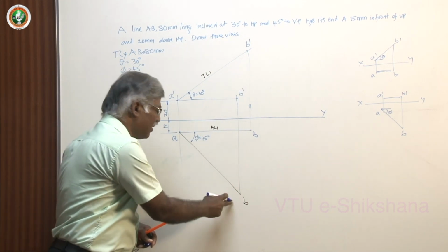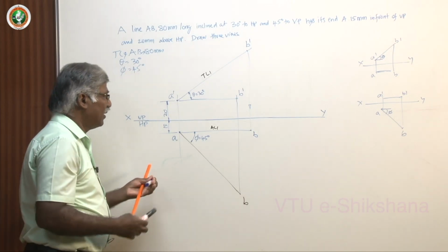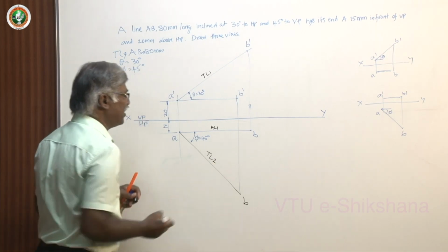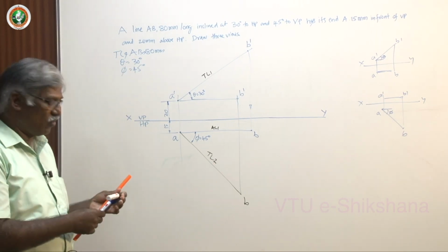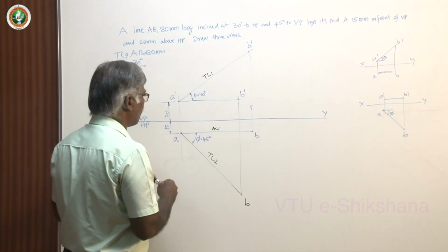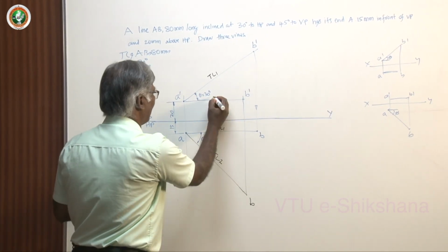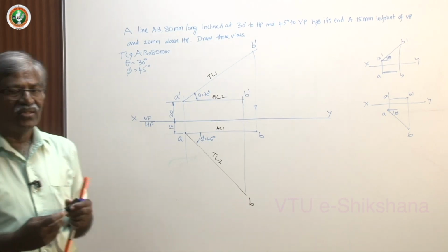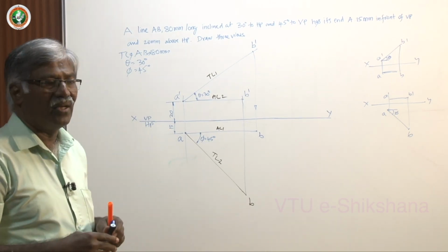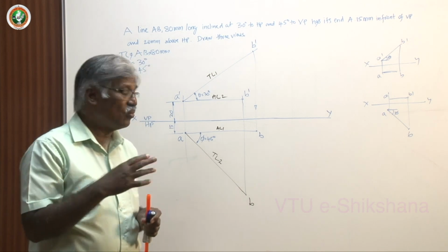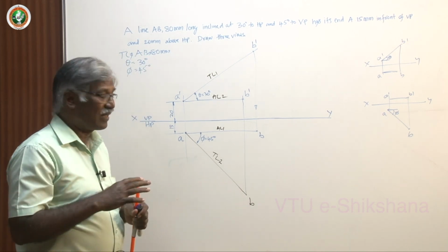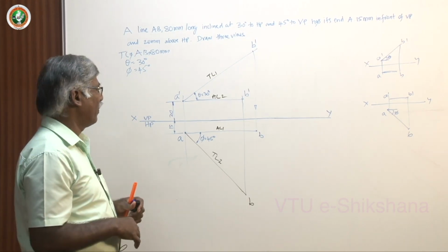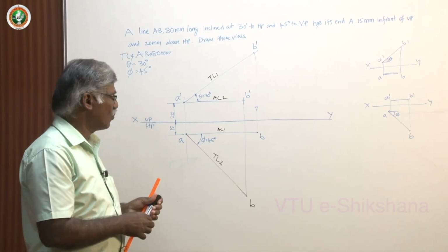Now this is the same true length, and I am naming this as true length 2. Even though it is the same, I am keeping it separate, because the position has changed and the corresponding procedure you have to follow. And this is true length 1, apparent length 1; this is true length 2, apparent length 2. So this is the set of basic figures one has to draw for completely understanding this straight line problem. This is again a very important figure also.